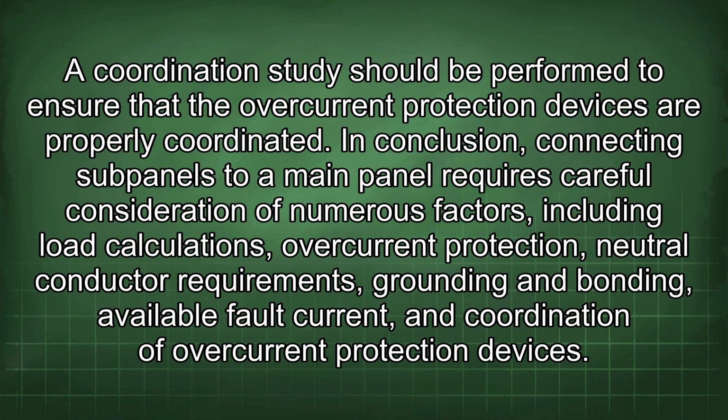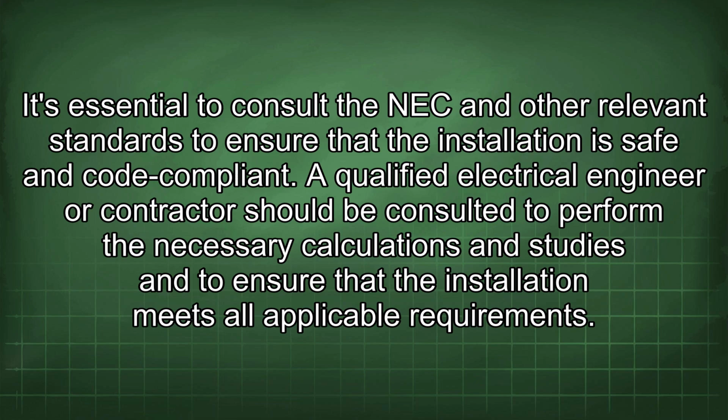In conclusion, connecting subpanels to a main panel requires careful consideration of numerous factors, including load calculations, overcurrent protection, neutral conductor requirements, grounding and bonding, available fault current, and coordination of overcurrent protection devices. It's essential to consult the NEC and other relevant standards to ensure that the installation is safe and code compliant. A qualified electrical engineer or contractor should be consulted to perform the necessary calculations and studies and to ensure that the installation meets all applicable requirements.